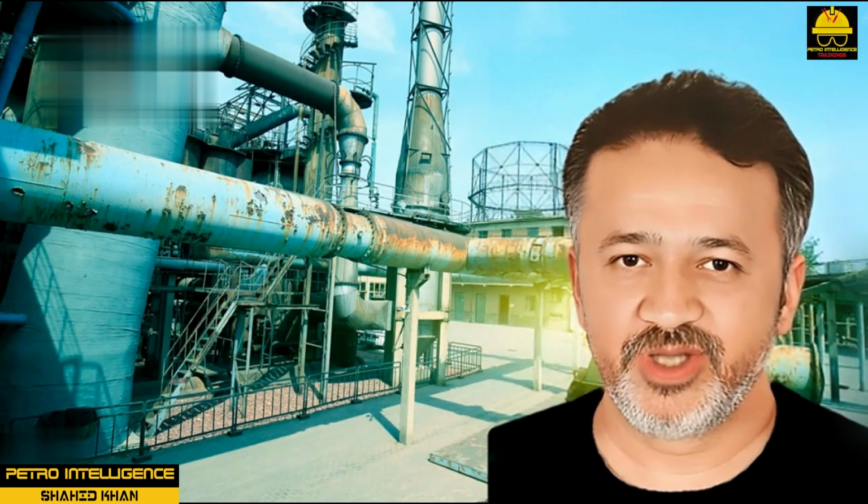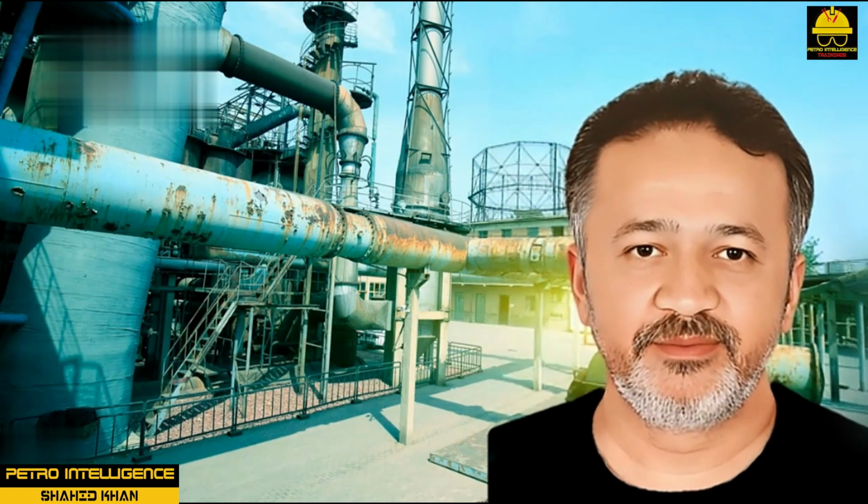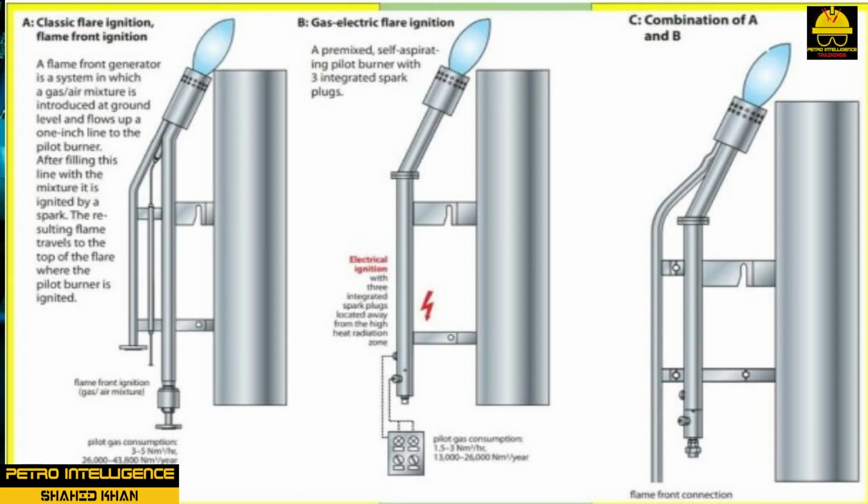Flare stack and flare pilots. The flare stack provides an elevated location for combustion in the flare tip. Flare stack elevation is selected to limit radiation heat at ground level. The tip is designed to allow smokeless flare operation at low discharge flow rates. Some flare systems are designed to handle only partial system or equipment failures without smoking.